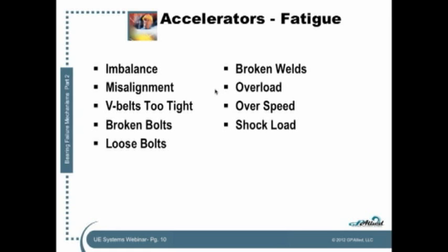Now, this isn't all of them. Poor lubrication will cause them, water will cause them, contamination will cause them. But if we're talking about mechanical drivetrain defects, this is a very nice list of what I'm calling accelerators, things that create these bearing defects that we're looking for. So this is our first lesson in condition monitoring technologies: there is a cooperation between the technologies to help paint a very complete picture of the health of your equipment. We're still looking for those high frequency defects, but we're also looking for these low frequency accelerators.